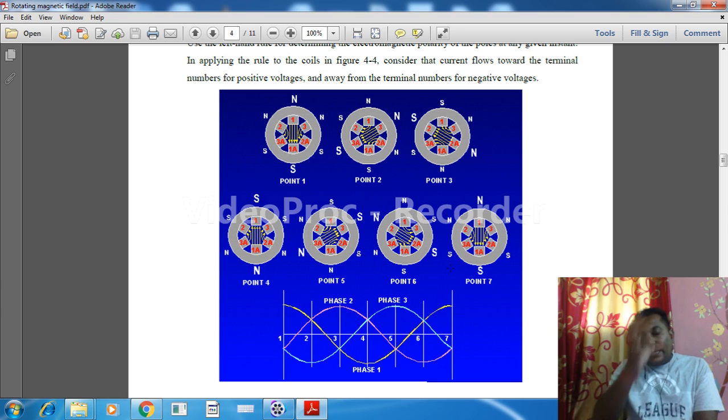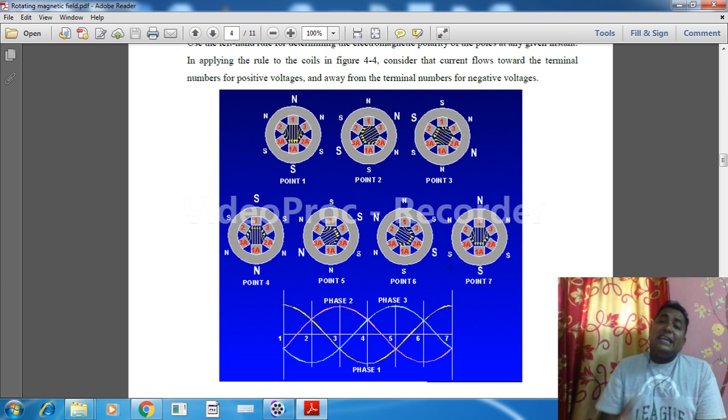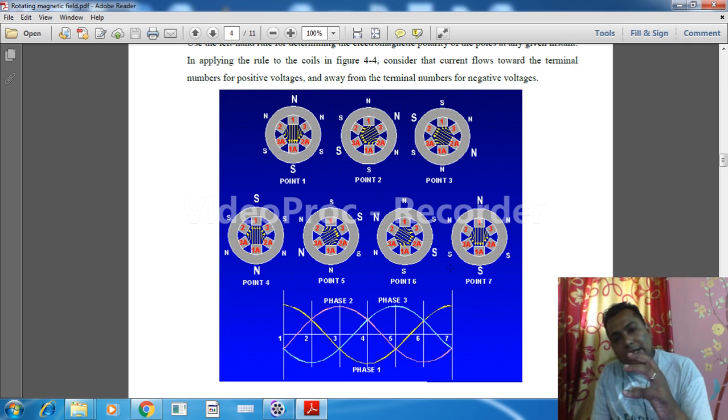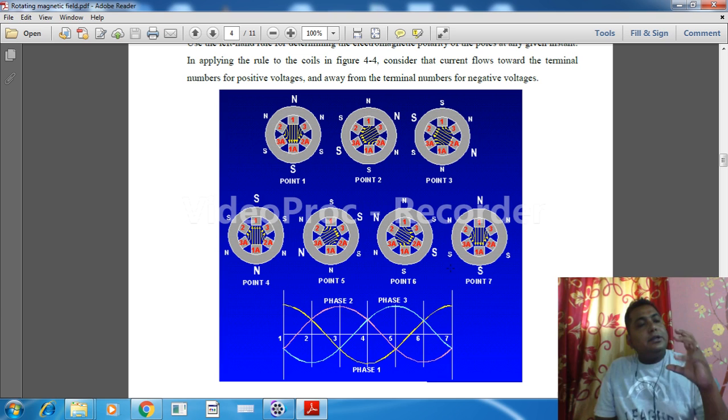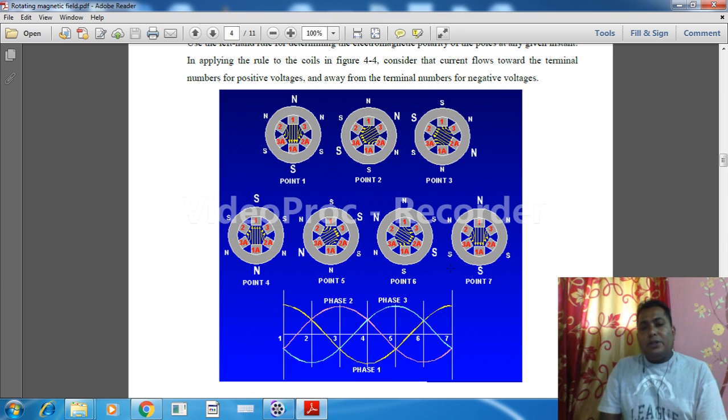So the magnetic field given as supply to the stator, it itself is rotating, and when we put a rotor inside that, and it faces some force, then due to that force and due to that torque generation it starts rotating. Okay, so that's why it is a self-starting machine. It doesn't need any other equipment or components to start over. That's in the three-phase induction motor. This is the very important characteristic.